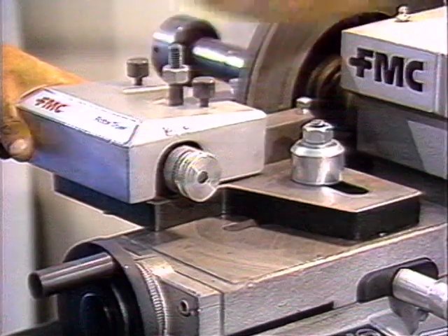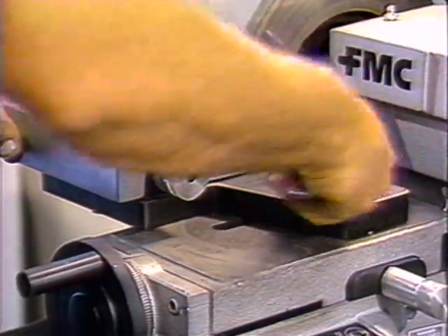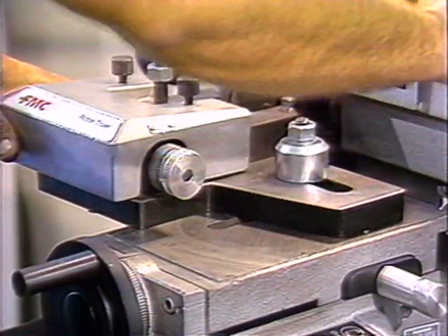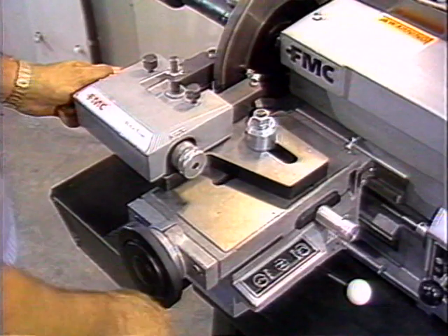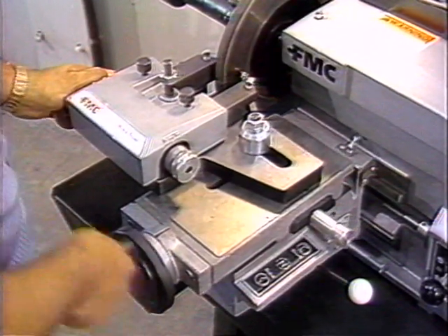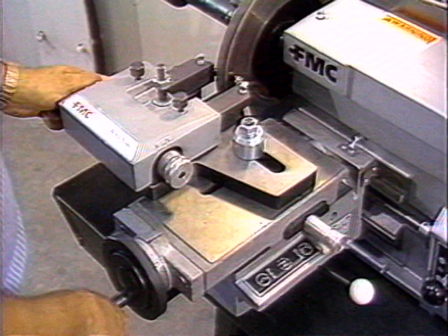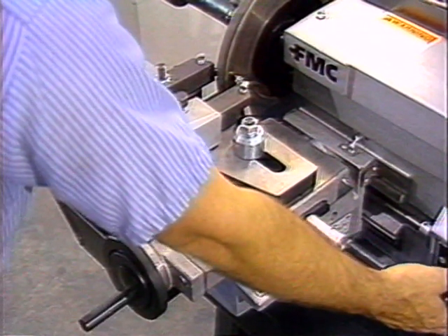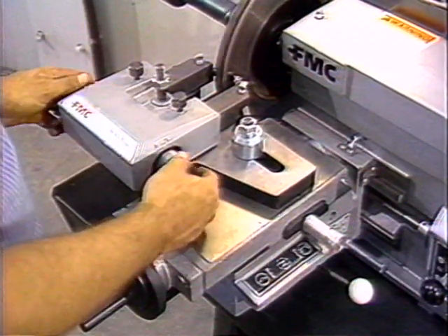Position the disc cutters on the lathe so that they can reach the inner edge of the rotor face. Tighten the pivot post nut with a rotor tool in this position. Turn the cross-slide wheel until the cutter tips are in the same general location where you took your micrometer readings.